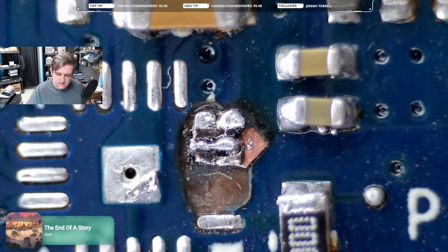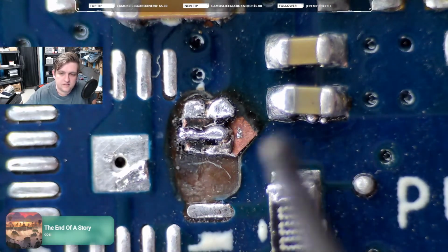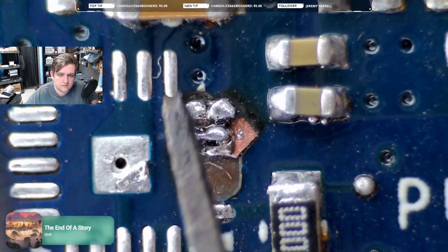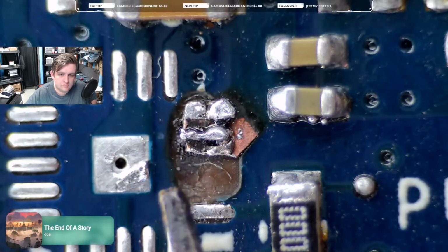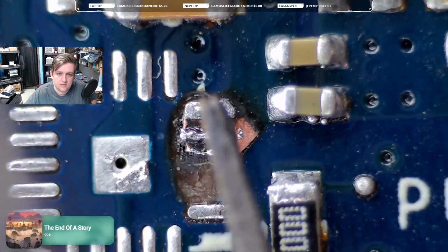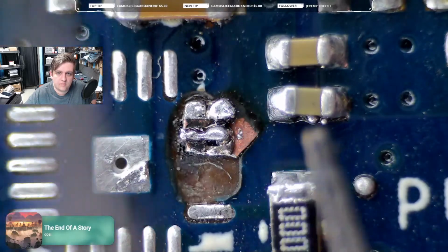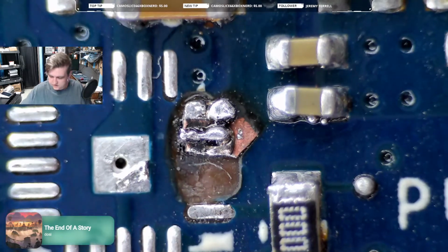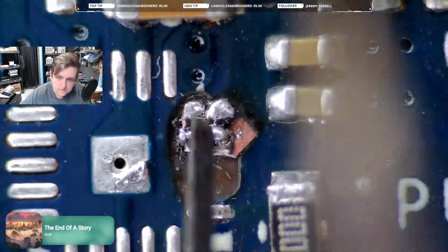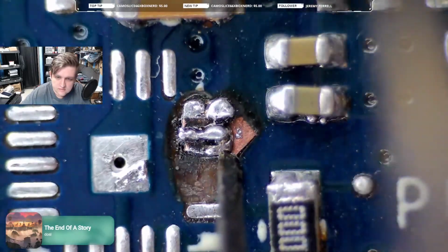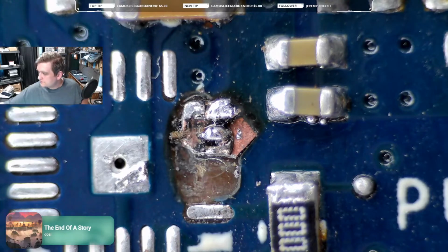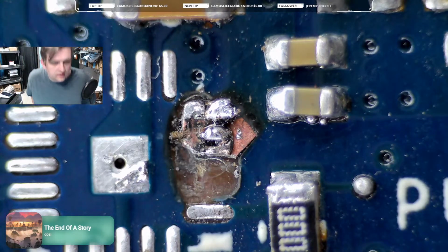So what we can do is get a pad strip, put it down, and then solder pins 2 through 5 on that chip. Whenever we get the chip back down, do 2 through 5 onto that pad, and as long as that pad's connected to this line here that goes straight to the cap, we should be in business there. So I'm going to go ahead and remove this here, since we've confirmed that they're all on the same lead. I might not be able to just grab it with my tweezers. No. I'll go ahead and get the iron back up and get that taken care of.